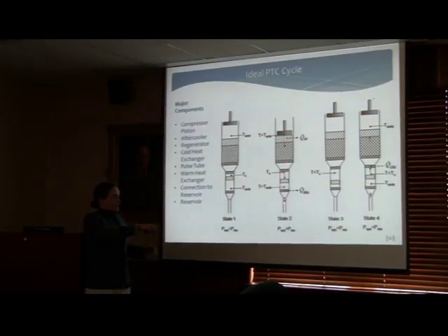The velocity is going to be moving this way, and it's going to expand the cold region, and this piston is going to compress the air on this side, and it's going to lose some heat through the warm heat exchanger. Now, when the compressor piston comes back up, because we have a shift between pressure and mass flow, the gas piston is going to stay in this location, but this section of air is going to get even colder.